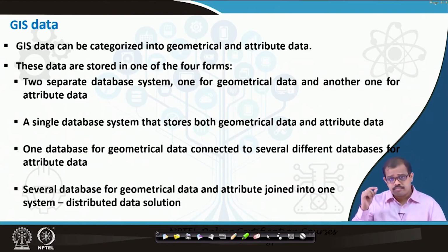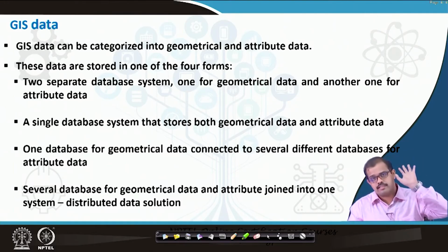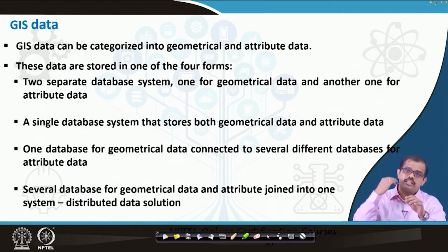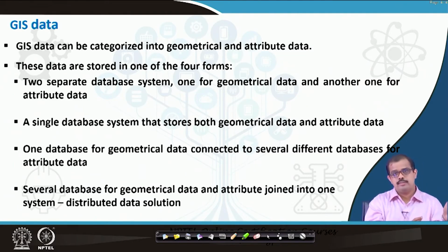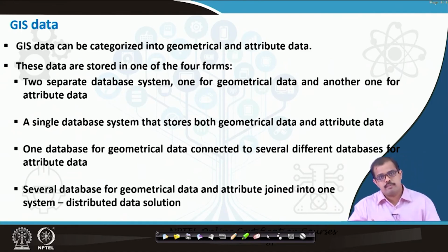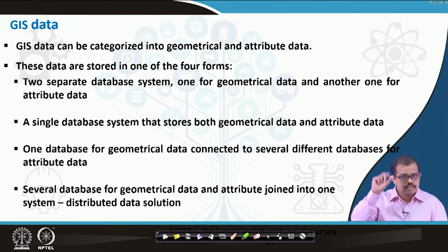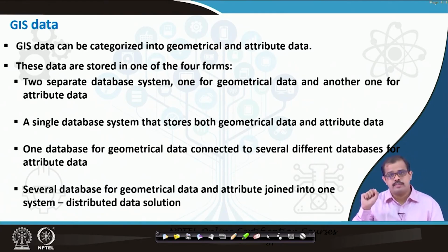So for these 4 different files, let us say someone sends only a single database system. It cannot sustain without the other things. If someone sends only geometric data, it cannot sustain without the other database because you cannot query it; it basically cannot open. If you have one file which has relationships only, it cannot open because it doesn't have geometric data or the other databases. So all these files have to be sent together in order to handle that data. If you want to send out the data to someone, it has to be zipped. Use WinZip to zip all these files and you can send it.